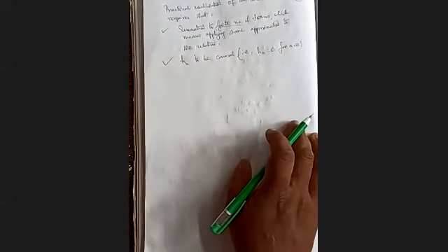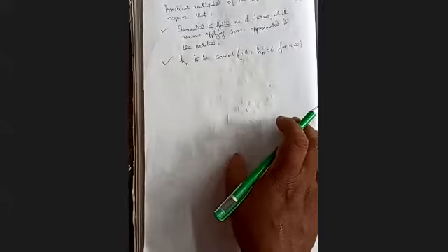These are the multipliers actually, but we cannot multiply anything with a future value. After we get a sample at some present instant, then only it will be multiplied. So all the present and past values will be multiplied, but future values cannot be. So h of negative n is not possible to realize at all. That is the second requirement, that it must be a causal filter.